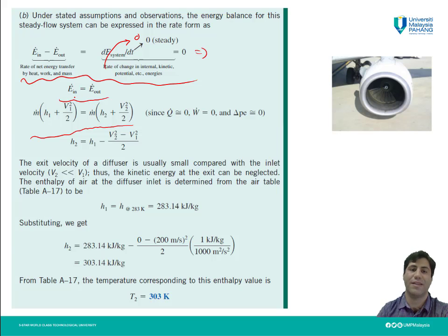which we have for the control volume at the entrance of the diffuser is the enthalpy. If you remember, at the entrance of the diffuser we have flow energy, which is PV, pressure and volume, and U, the internal energy. And as you remember, we use enthalpy instead of these two for simplification.